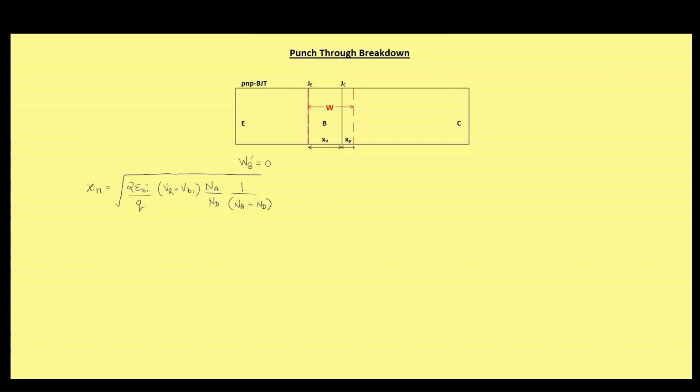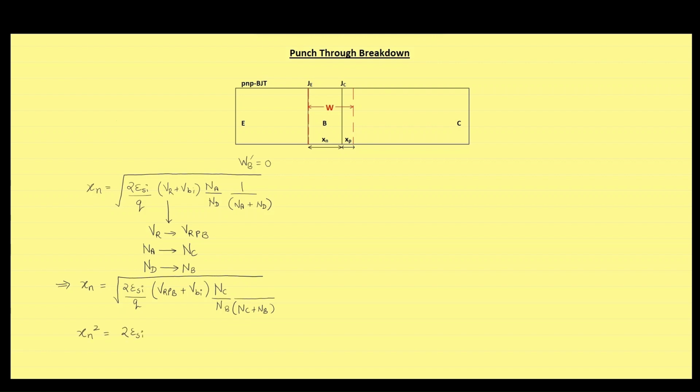Therefore, we will replace a few symbols: reverse bias voltage will be replaced with the reverse bias voltage corresponding to punch-through breakdown. Similarly, we know that Na represents acceptor impurity, and here in our case p-type is the collector. Therefore, acceptor impurity concentration will be replaced by collector doping concentration. Similarly, donor concentration will be replaced by base doping concentration. So, for the BJT, the above formula will change to... Now if we square on both sides, we will get...